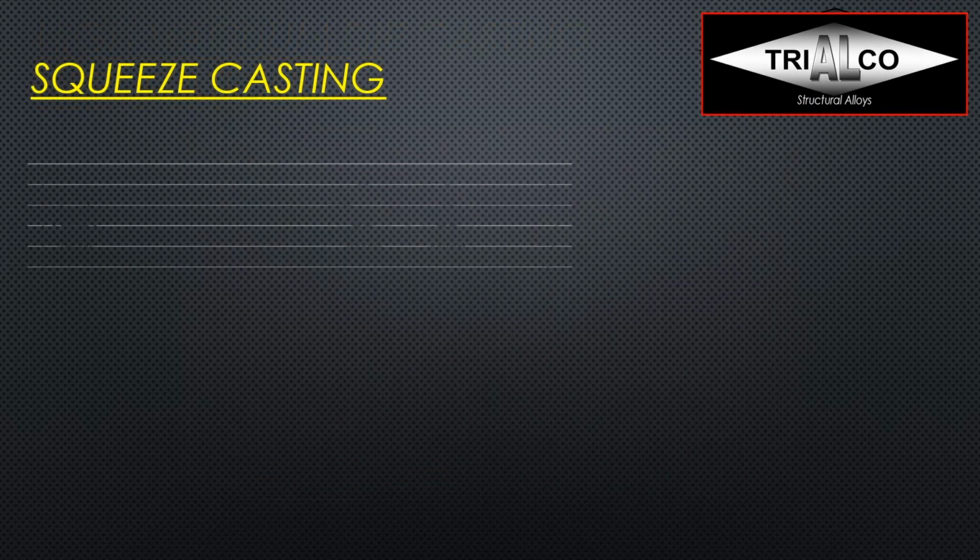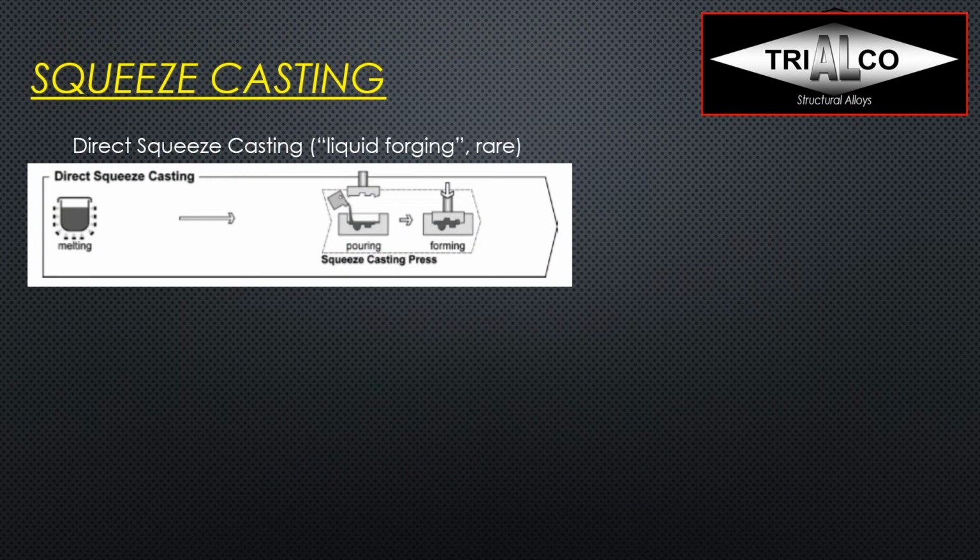So now let's talk about squeeze casting. And we won't be getting into direct squeeze casting because that's called liquid forging, which is actually a better name for it because it's ultimately like a forging press, but instead of putting a heated billet that you would then forge into a final shape, you actually pour liquid metal in the bottom part of the mold and then squeeze down from the top with the other half of the die. And with that, you create your final shape of the part. It's a pretty rare process, and there's one place in North America that does it that I'm aware of. Of course, it is a high integrity process and makes very good parts.